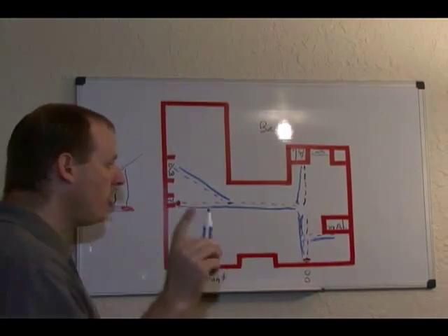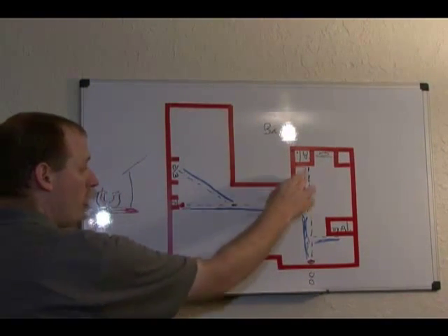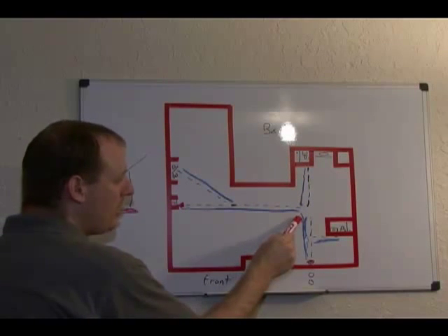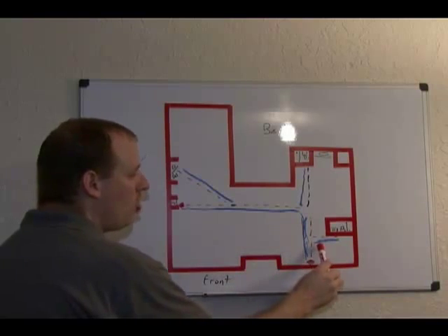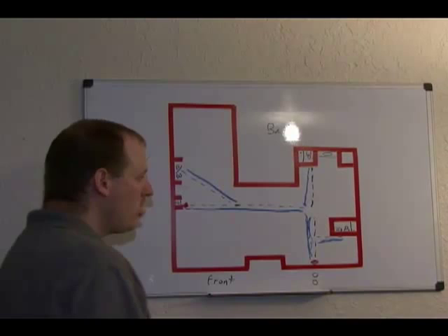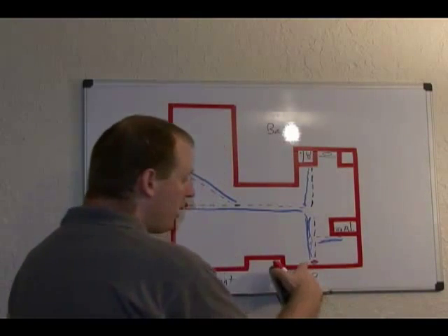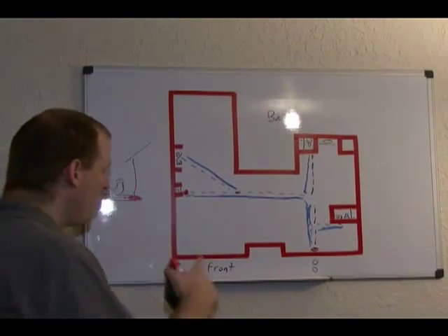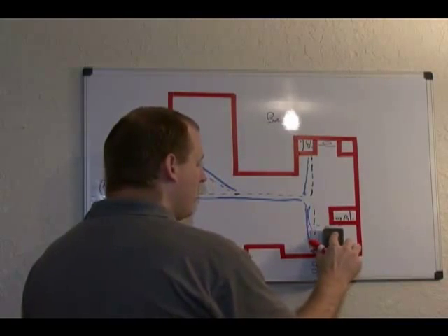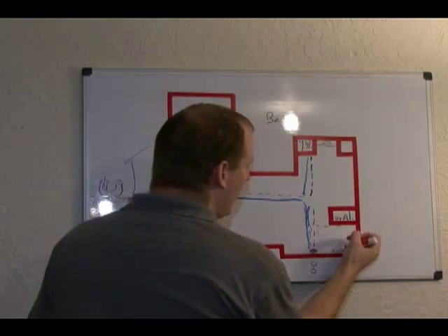At that point, the only possibility for where the leak is, based on the fact that we've already tested this and showing there's no leaks, is there's got to be a leak in this line or in this line under this bathroom, etc. Okay? So, at this point, we would then place a test ball. We can leave our test ball in there. We can leave our test ball here. We've got all this water in the line, so no sense in taking it out of the line. Okay? We would then place a test ball right here.